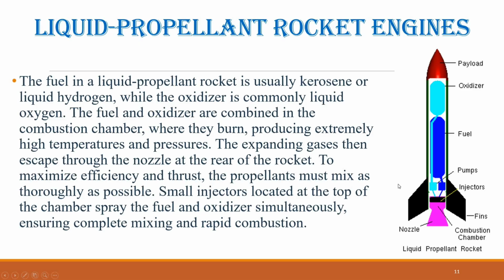However, the extreme heat and high-speed gases passing through the nozzle would quickly melt thin metal walls, so a cooling system is necessary. One highly effective cooling method takes advantage of the extremely low temperature of liquid hydrogen. Hydrogen becomes a liquid at -253 degrees Celsius.